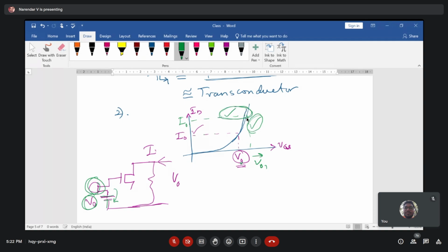So as you increase the V naught value, it leads to draining of your battery very fast, which is not a suggestible choice for the value of V naught. It should not be so far from the VTH value. So let's say here it is VTH.